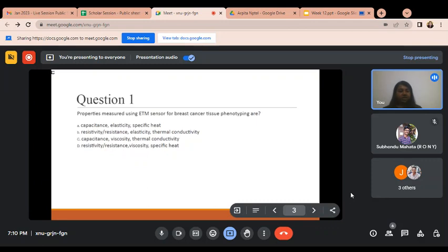So it is another type of contamination. For that case, we dip the wafer into the DI water, so the remaining solution present on the wafer surface can go out. Then after the DI water dip, the wafer is dried using nitrogen gas flow. So this is one type of wafer cleaning process.